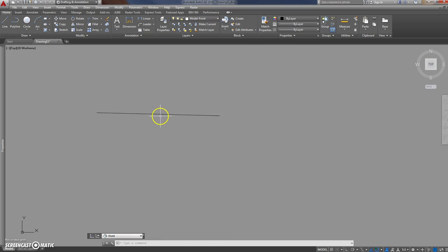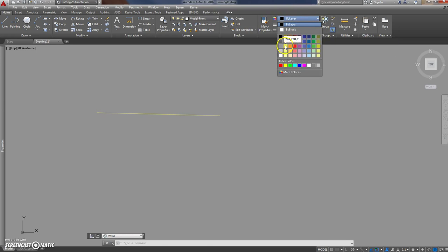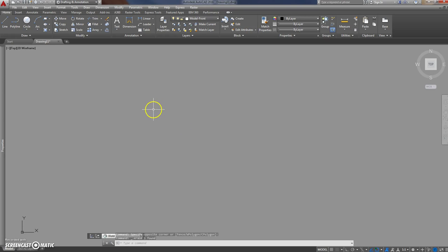But if that line was, say for instance, made to have the colour yellow, which is not to be recommended by the way, but you can actually do it, you can change the colour of that line to say yellow. Then it becomes harder to see against a lighter background. So click on there and delete that. You press the delete key.